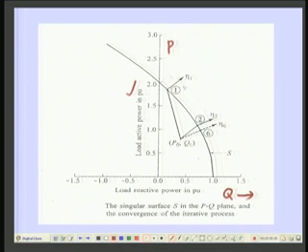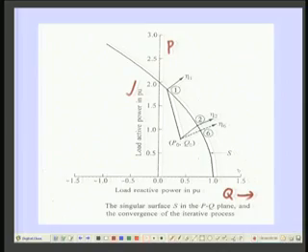Now, we can find one surface such that any point on that surface, if you operate at that point, will lead to voltage instability. In case it is a large system with a number of buses, that surface comes out to be a hypersurface. In this particular case, in a simple radial system, we actually get a curve. Now, this is the curve.